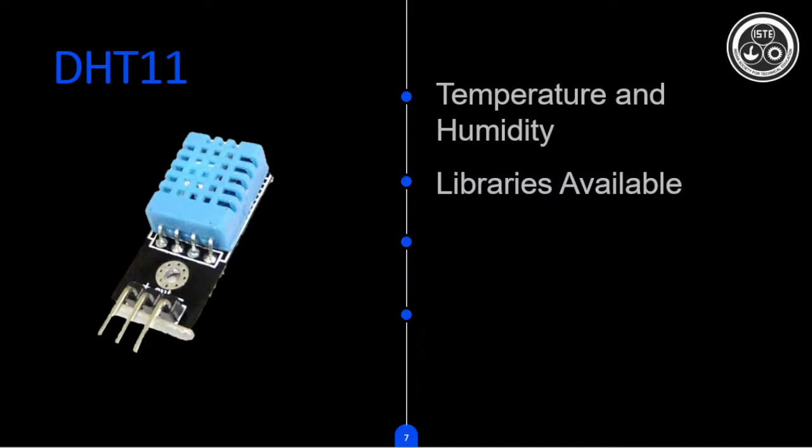As I said, first we need to give a start bit, then send a message signal and receive a checksum and stop bit. So you need to write everything manually if it is a digital sensor and the libraries are not available in open source. But in our case, the DHT11 library is available as open source on GitHub and in the Arduino libraries too. I will be showing how to download those. It makes our work much easier.